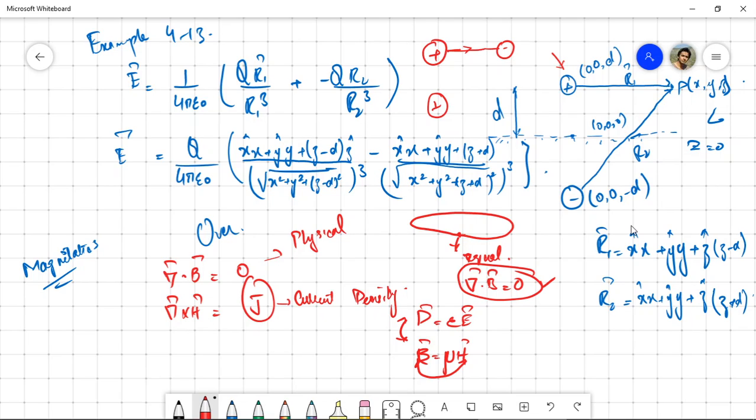At that point, the values of B and H are not linearly linked, because the increment in the magnetic field intensity is too high, but the increment in the value of B is too low. We will study the science behind that when we study ferromagnetic material in a little more detail.